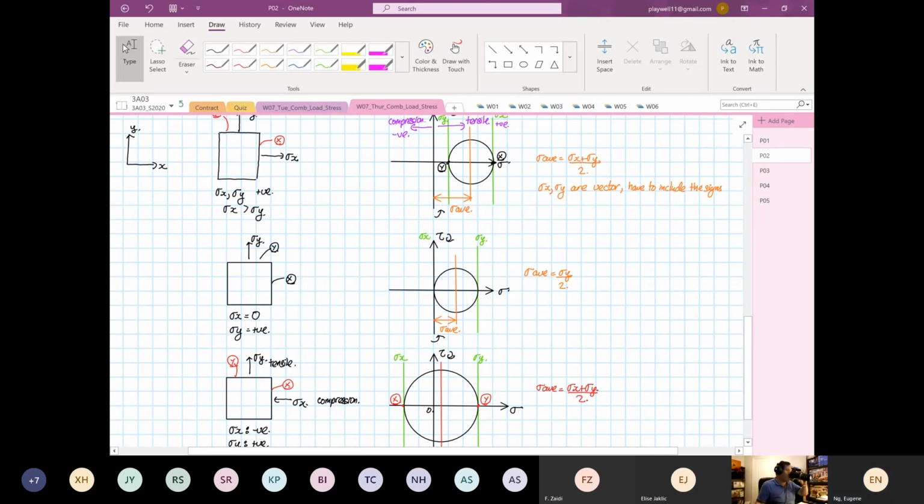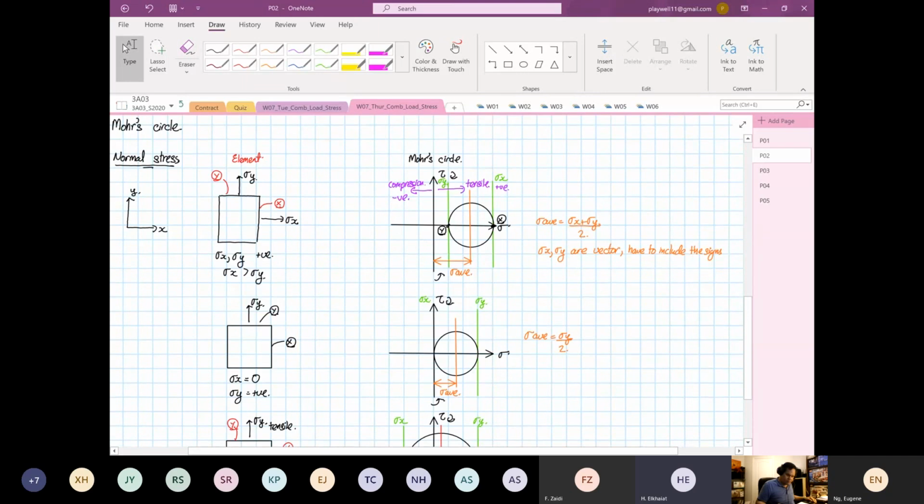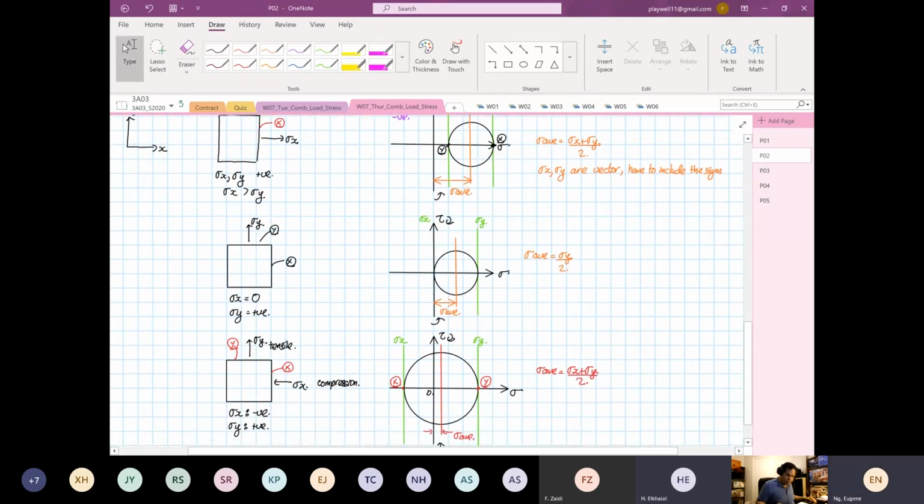Yes. Eugene, how does constructing the Mohr circle help you in choosing your material? Like we have some that have greater average stress than others, in terms of your Mohr circle. What do you get from that? What's the understanding? The average stress cannot be used for selecting material at all. It just tells you where the center of the circle is.